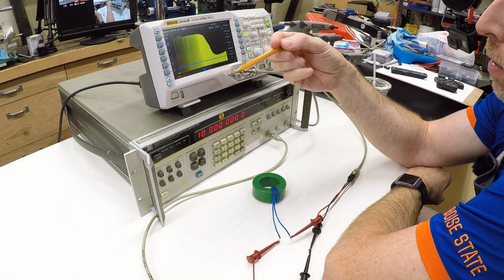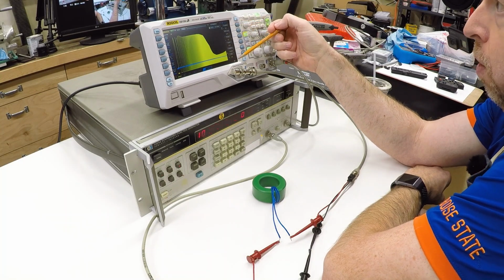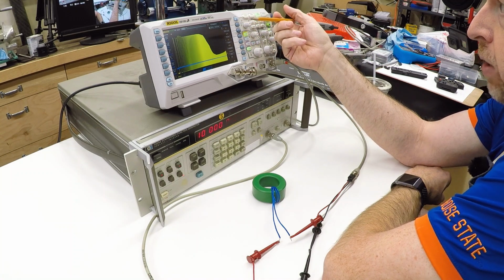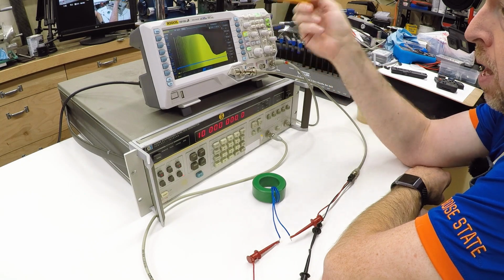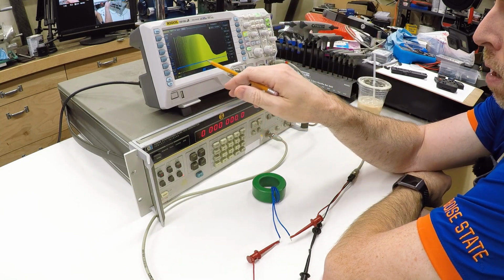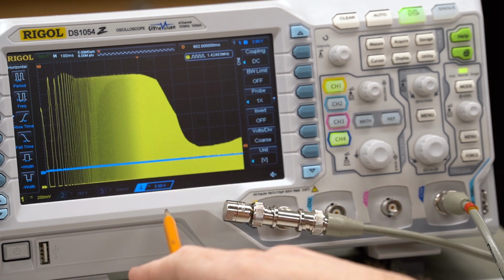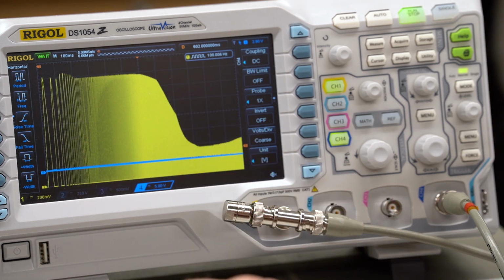And if you look at this, you can see this is 10, 100, 1 kilohertz, 10 kilohertz, 100 kilohertz. So right here, we've lost about half of the amplitude right at about 100 kilohertz. Now, ideally, you would have the Y also logarithmic, so you could read this off in decibels, and if we had a real spectrum analyzer, that's how we'd be reading it. But this gives you a good idea of what the amplitude looks like, and if you remember from the bode plots we looked at before, they looked very much like this.